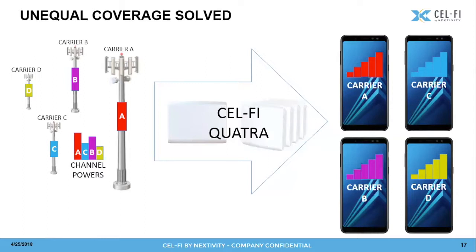Yes, and that's a very, very good question. To first talk about it from the bidirectional amplifier perspective, it has no idea what channels exist in what portions of the frequency of a given band. It has no idea, which means you'd have to use extra equipment outside of the system to try to figure out if your power is being robbed by a specific carrier and if you're being shortchanged by somebody else. So it would be a very manual process with expensive test equipment in general to find out.